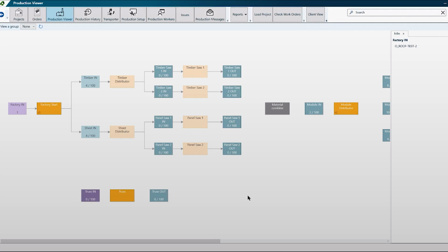Stacks are a very useful way of making it so that you cut it and you put all of the stack material onto a trolley, and then that can be used to be assembled into panels, floor cassettes, etc., without having the issue that the software prevents, the person on the saws, the sawyers, having to actually then sort out into the trolleys, that stuff is going to that bench, that stuff is going to that bench, and so on and so forth.